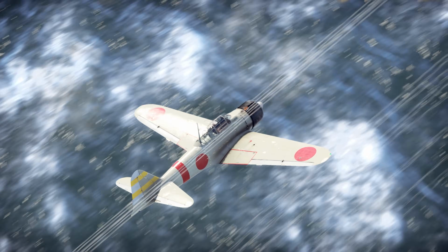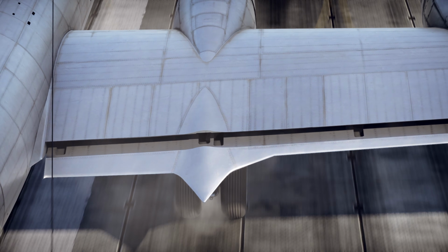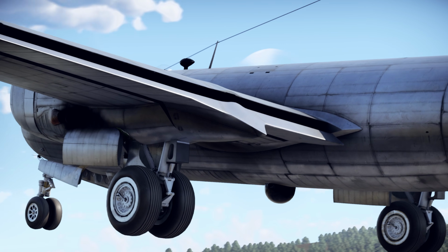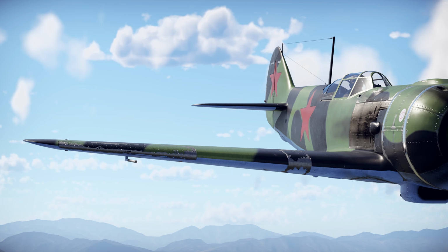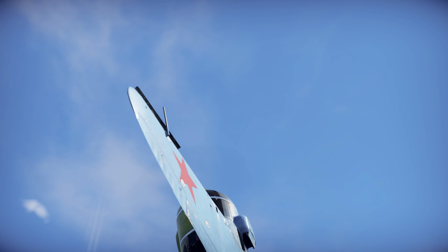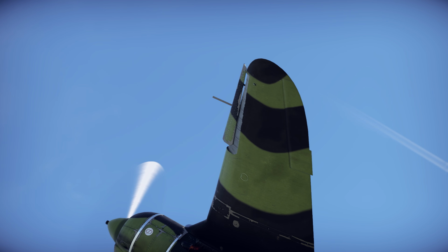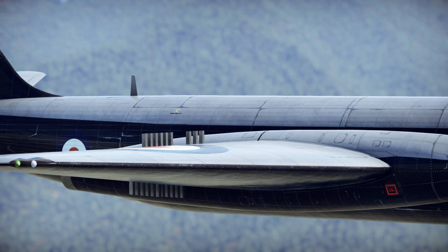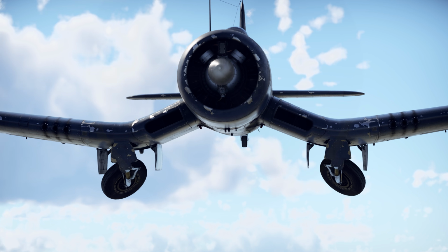Additionally, flaps may be installed on the trailing edge of the wing near the fuselage to increase lift. Leading edge flaps can be found on the front of the wing to prevent airflow separation at high angles of attack. To reduce speed, aircraft employ various air brakes that increase drag, and these come in the shapes of flaps, spikes, and even landing gear.